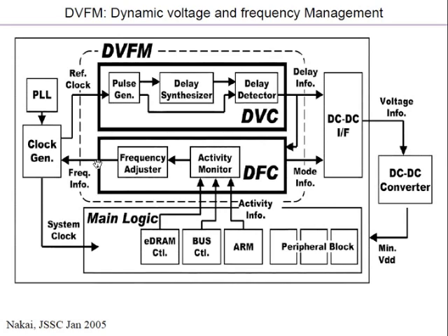Now once you have adjusted the frequency, you hunt down the voltage using the critical path model such that you use a voltage which is just optimal for that frequency. So both frequency and voltage keep getting adjusted in this continuous fashion. The overall system, this chip, has all of this. They have shown this in a very big way, but the actual area for this will be small. Most of the area will be all this other stuff.